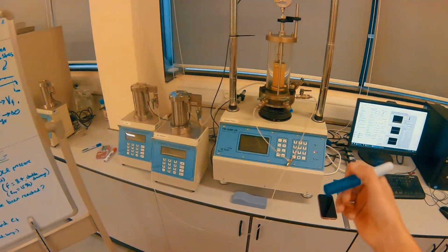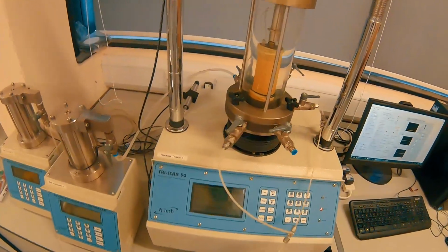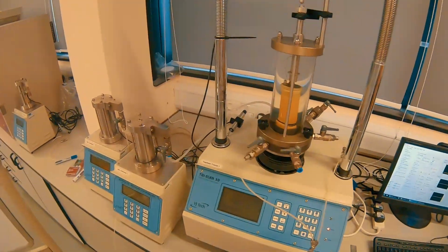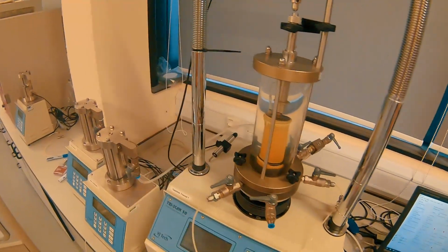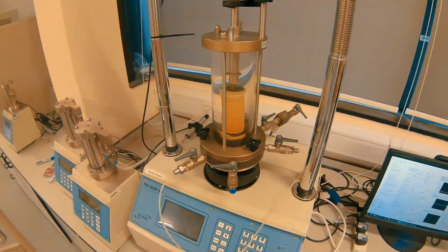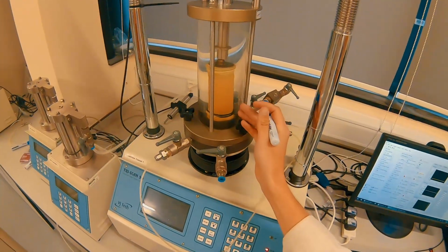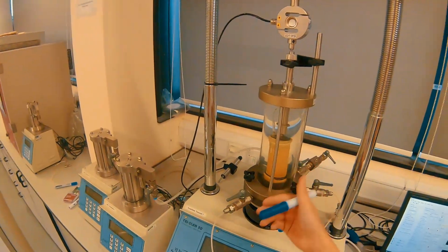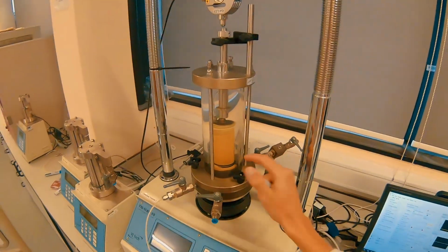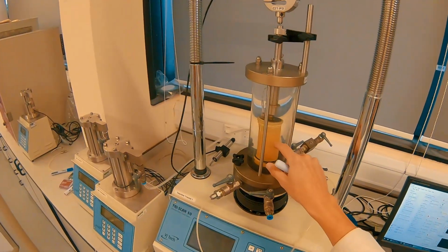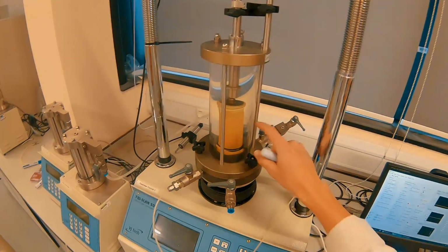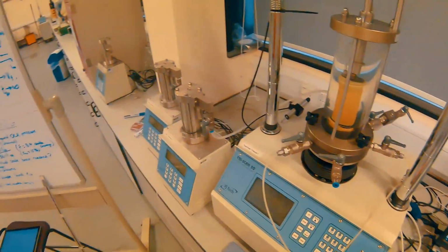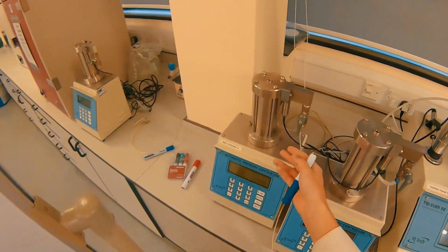What does that look like in our sample? We have the back pressure controller line here, and we have the cell pressure controller line. The cell pressure is going to increase. With the pressure staying the same in our sample, which is sealed by the O-rings and the membrane that we looked over in the first video, the water within that sample is going to flow out of these lines in double drainage back into our pressure controller.